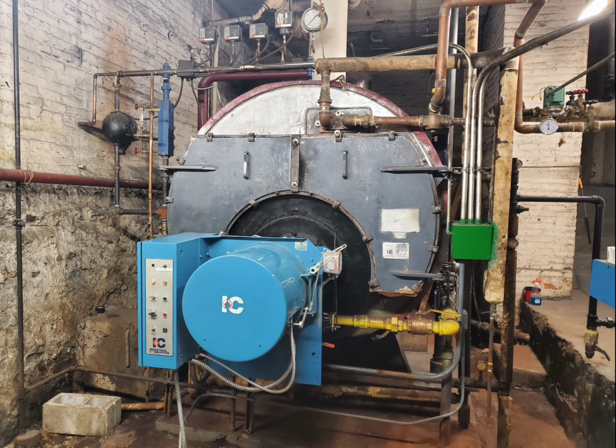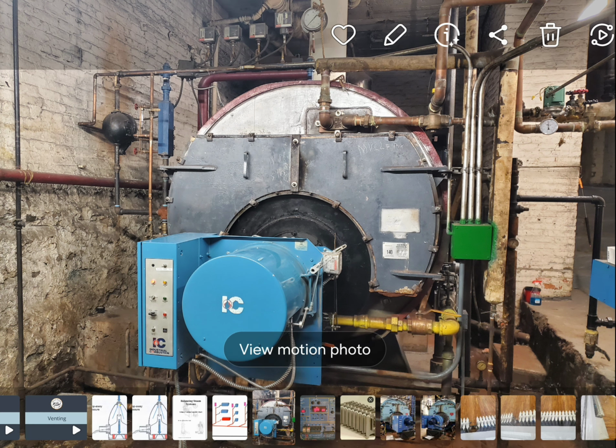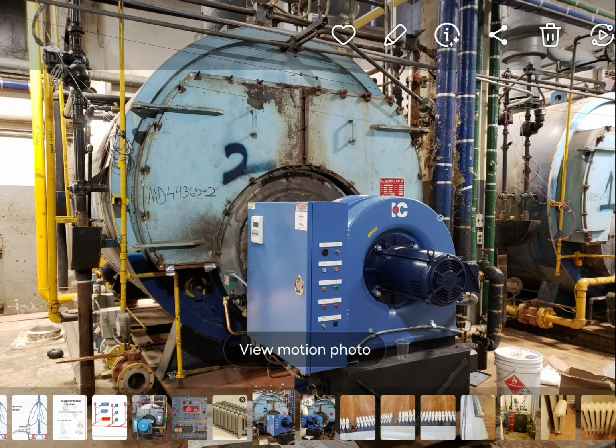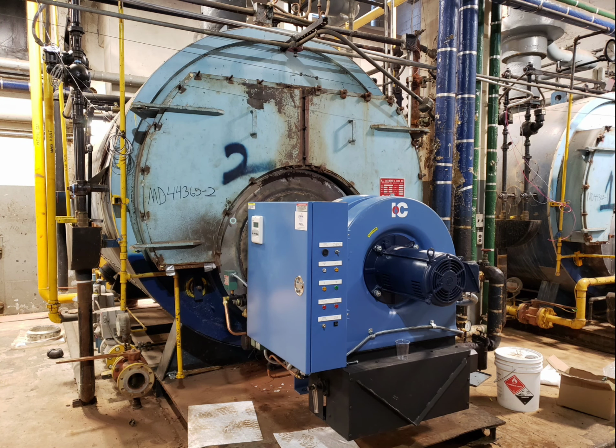But I've seen these things take even up to 2 minutes of just purging air inside of the combustion chamber. Now your boiler, this vessel right here, is nothing more but a big heat exchanger. Let's go back to this one. Inside of these doors are hundreds of fire tubes. Okay, it is nothing more but a big heat exchanger. And without a burner, your boiler is essentially heartless.